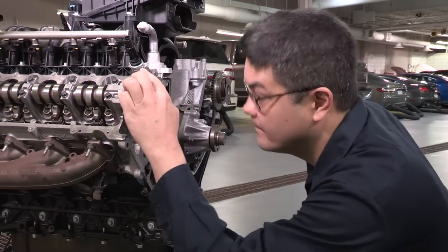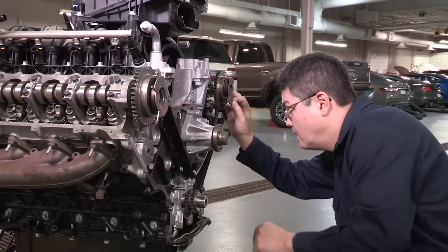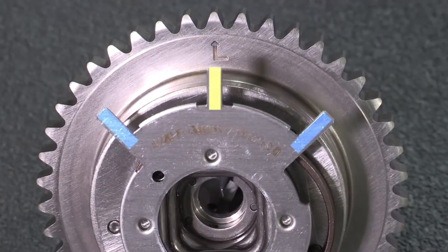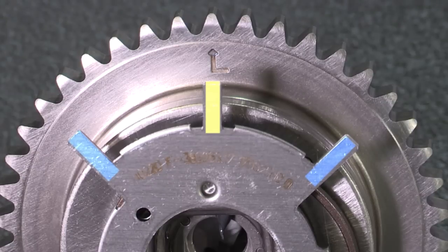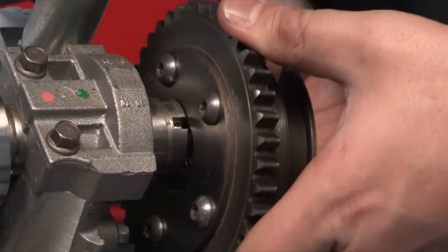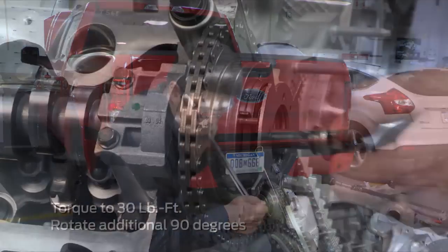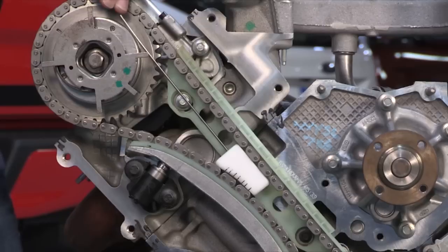You may need to visually inspect the VCT phaser indicator fingers on the left and right heads. There are 5 indicator fingers on the VCT phaser. The odd finger should be directly over the letter L on the VCT sprocket while in its normal resting state. If the indicator finger is rotated too far clockwise from the letter L, damage during installation or reinstallation could have occurred during the torque to yield sequence. See our Tech Talk video on VCT phaser installation for more details.